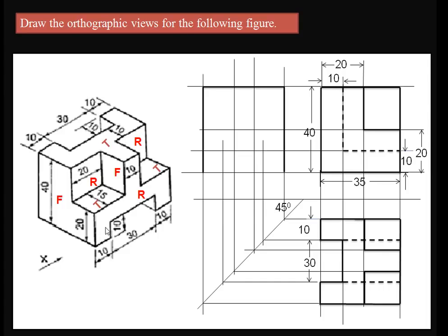Now I would like to draw this edge wherever I am showing my cursor here, which is equal to the length of 10. So we need to draw here 10, and similarly draw another edge which is again at a height of 10, so already represented here 10 line. So now again join this until it will intersect this construction line, which means this edge point to this edge point will be showing.